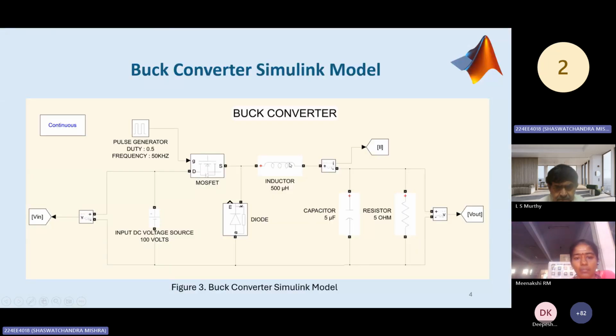Okay. So here we conclude our buck converter journey. Now we will next move on to the design of its gate driver, right? So why do we need a gate driver actually? We want to give the MOSFET some duty ratio, some pulses. It will be turned on and turned off for certain time. So in order to do that, we will be using a microcontroller. We will be programming a microcontroller such that it will provide a high pulse for some time, and then it will provide an off pulse for some time.